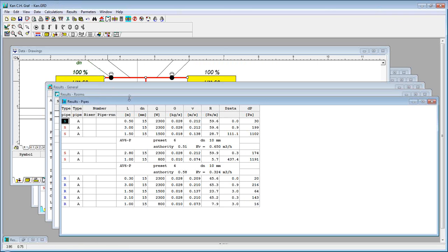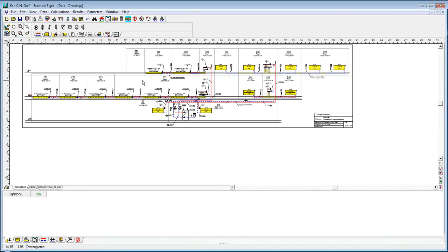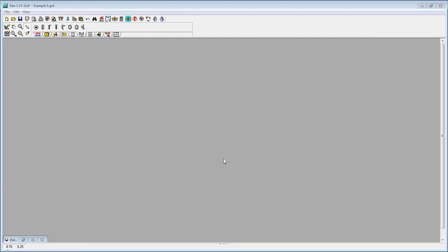And the program also enables us to design the systems with underfloor heaters, and I would now like to present it in a short way. So let's open the example 5, because it's already with these radiators. And really the designing of such a system has got two steps. First, we design the construction, the types of the radiators, because in case of the convection radiator, they are designed in the factory, and in case of underfloor heater, we've got more flexibility.